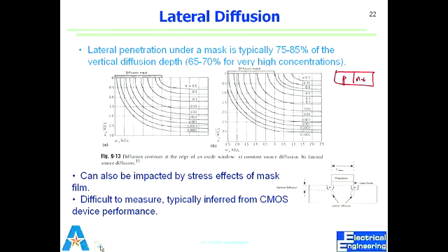You can measure the sheet resistance. Just have a probe and make it travel downwards. It's essentially how it is done, right? But those probes are very, very, very fine in the tip, because now they have to measure how the sheet resistance changes, right? And that can relate to our profile. How can I measure vertical or lateral diffusion that has occurred? How can I measure lateral diffusion?